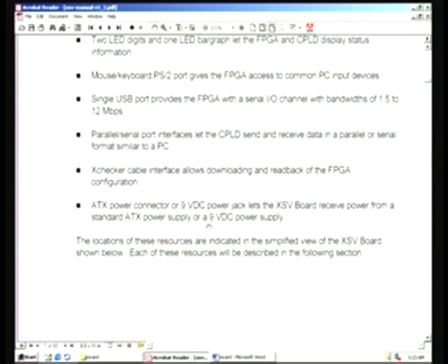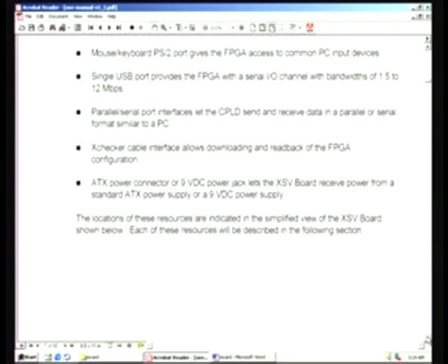So that is what you have to take into account, and normally the board demands 5 volts and 3.3 volts, perhaps 2.5 volts DC is also required, and all are derived right from 9 volts which we can supply externally, or you can supply from this ATX power supply, and so having seen all these features of the board, we can now see pictorially how the board looks like.